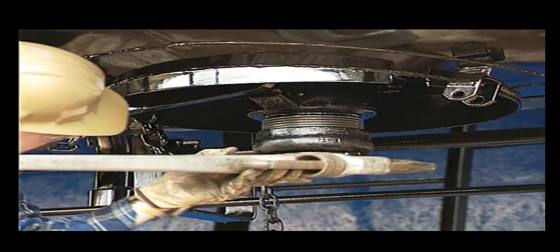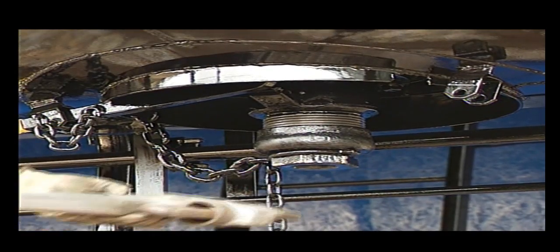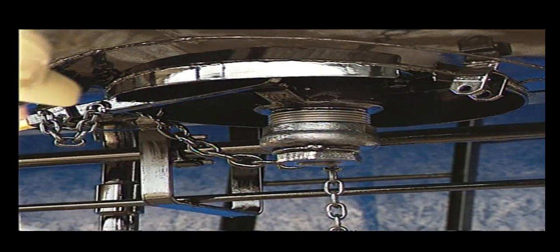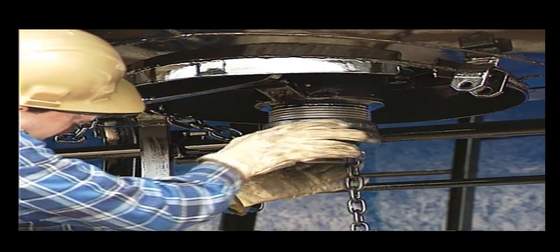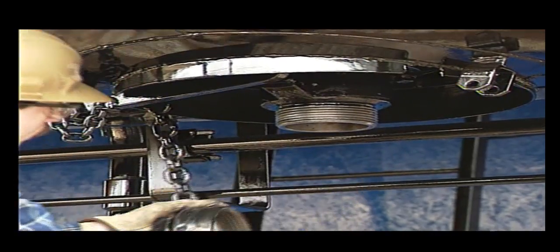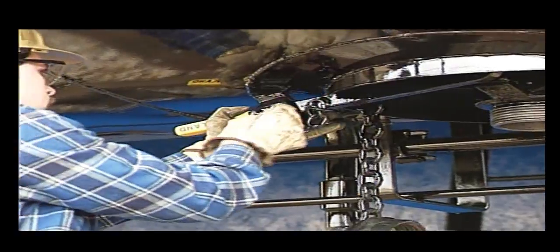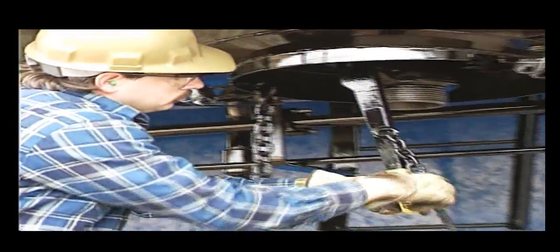The next valve we'll discuss is the bottom-operated plug valve. This valve appears similar, but unlike the previous valves, the nozzle extension is an integral part of the valve. It houses the operating mechanism, where a standard cap and plug are used. To open the valve, rotate the handle 180 degrees and pin it so it will remain in the open position.